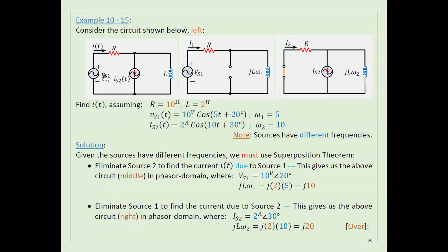Okay. Now I will come to the last example you have here, guys. I made it very clear: when I analyze these circuits, I have to make sure we only use one omega. You get one value for omega, because by changing omega, you change the circuit. By changing omega, all impedances change, so you change the circuit. Even in the calculation, I delete omega, I don't use omega, because all the math is in omega.